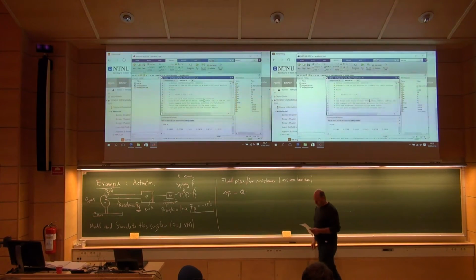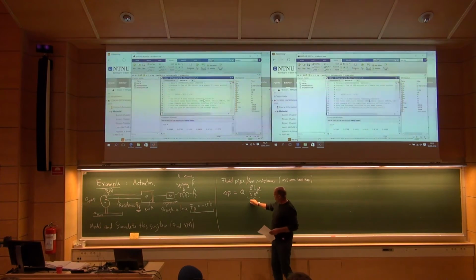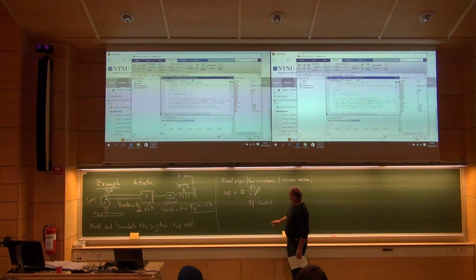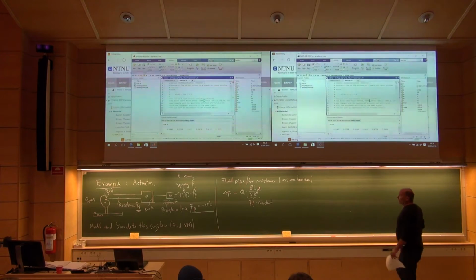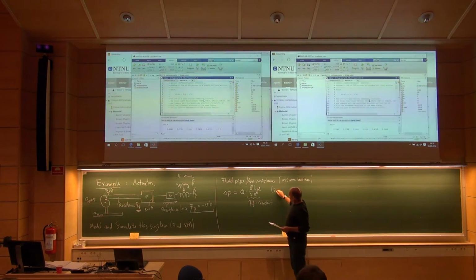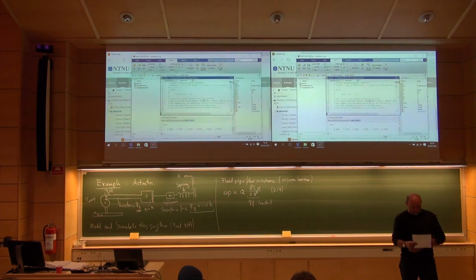Here we multiply now with a parameter, and it reads 8 times the length of the pipe, viscosity, over pi, radius to the power of 4. And of course, this is just parameters, so here we call it R_F, which then is a constant. So pressure drop due to friction is proportional to the volume flow. That is actually equation number 2.14 in chapter 2. So we will address general resistance there.